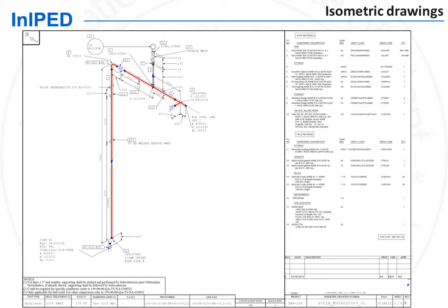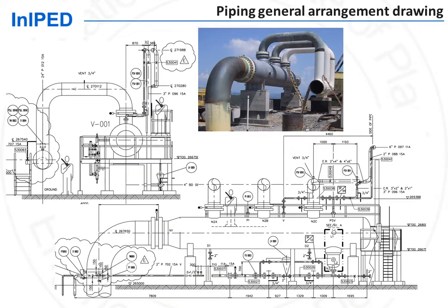Another type of drawing is issued for piping erection, the piping general arrangement drawings. It must be said that these drawings tend to no longer be issued today, as extracts are made instead from the 3D model. These drawings are nevertheless issued at the end of the job to serve as future reference for the plant owner, as they show the complete equipment environment.